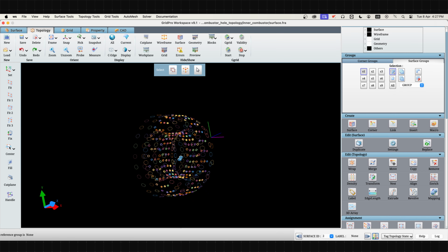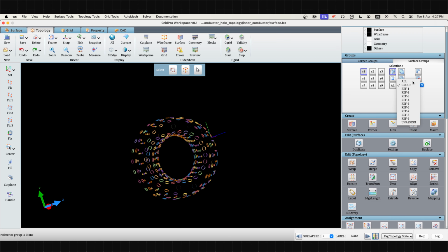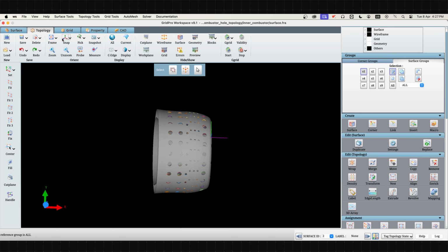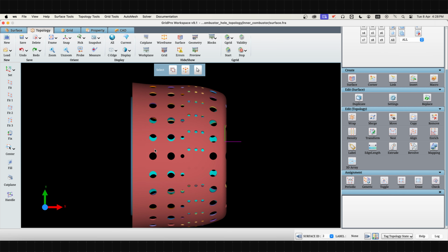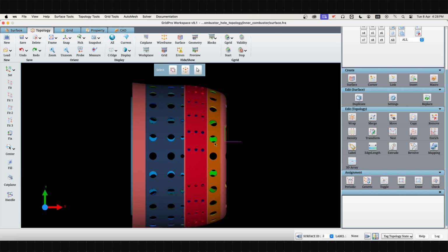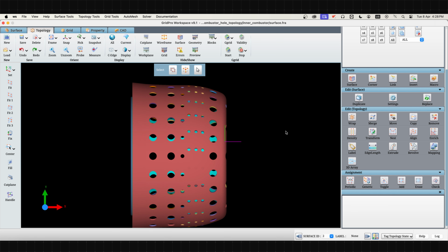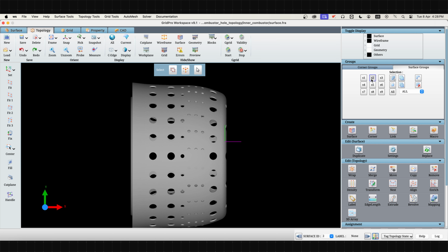To enable automatic linking of hole topologies, we'll organize the holes at the same axial level into separate surface groups. Visually, the holes can be classified into 4 distinct groups based on their alignment, each group containing holes that can be linked both vertically and horizontally. Let's first copy the hole surfaces into new surface groups, keeping only those at the same axial level.